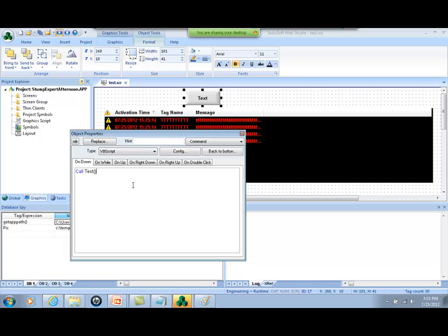In some cases, you want to trigger the function from the web thin client, but you want to make sure that the function is executed on the server. For instance, if you want to save a file on the server or load values from files on the server, then you can use the InduSoft built-in function RunGlobalProcedureOnServer.